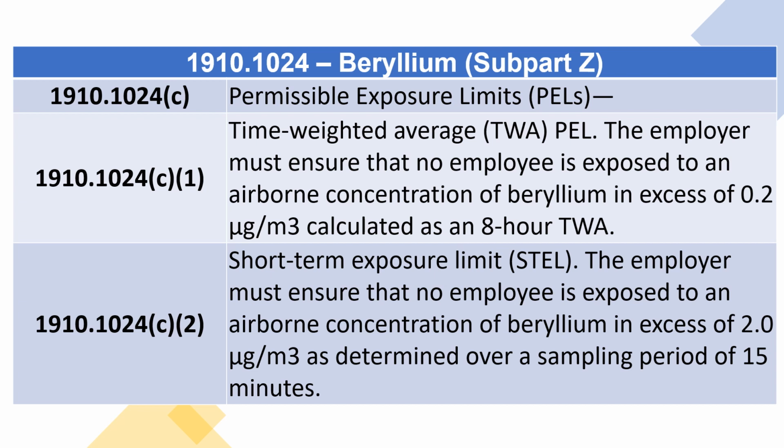1910.1024(c)(2), short-term exposure limit, STEL. The employer must ensure that no employee is exposed to an airborne concentration of beryllium in excess of 2.0 μg/m3 as determined over a sampling period of 15 minutes.